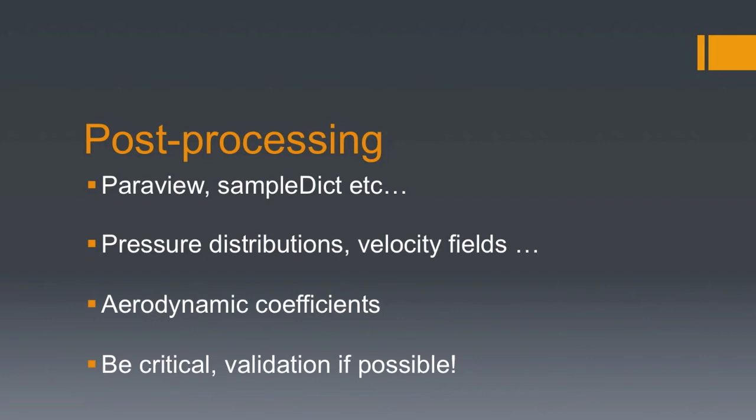Never trust CFD models without proper validation. Most of the problems result from turbulence modeling, and for example, the standard k-epsilon model used in this case usually overestimates the turbulent viscosity and can't properly estimate the flow separation.